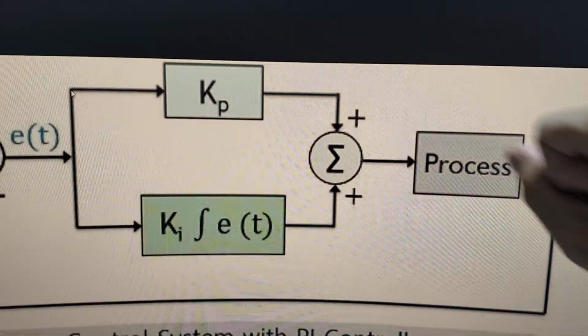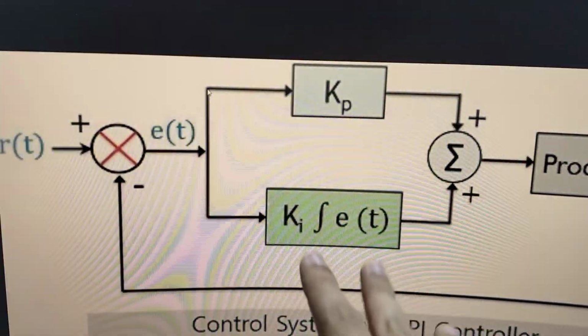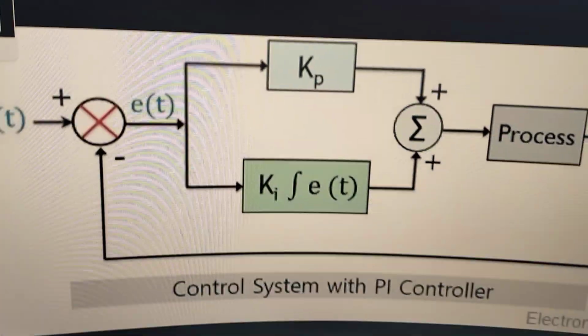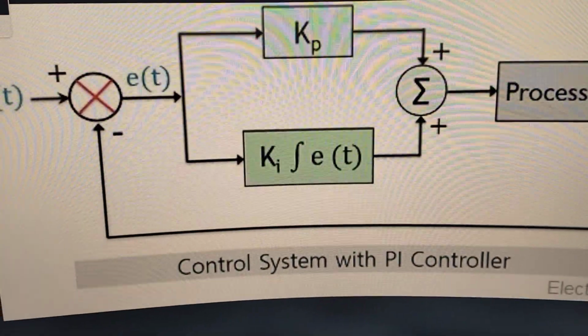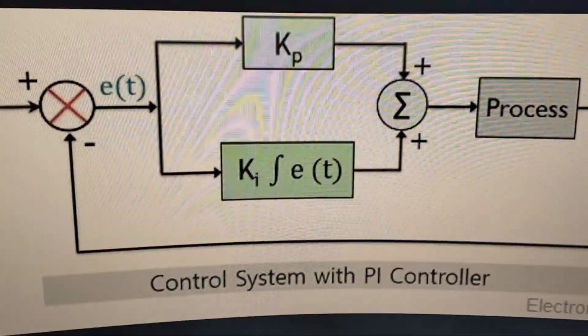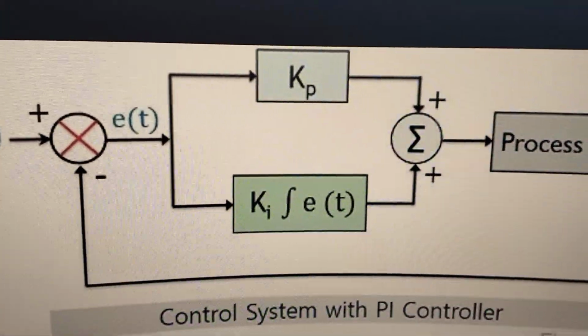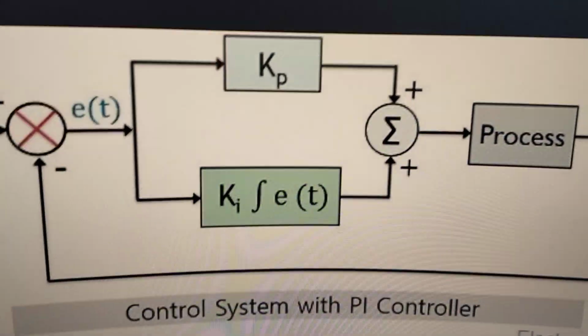So currently our plant is basically the buck converter, and if you tune these well enough, you should reach your set point. Of course you can implement this PI controller in discrete. They do it with op amps and all the capacitors and resistors, but it's a bit of work and a little cumbersome changing all those capacitors. So these days, of course, we all do digital control.